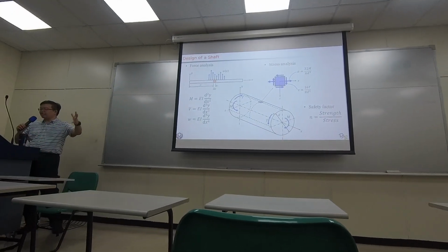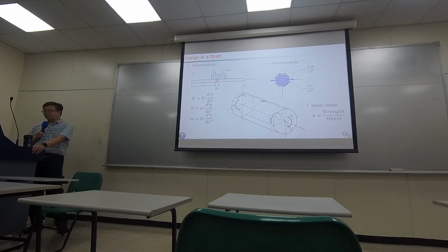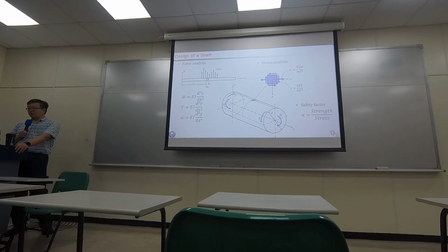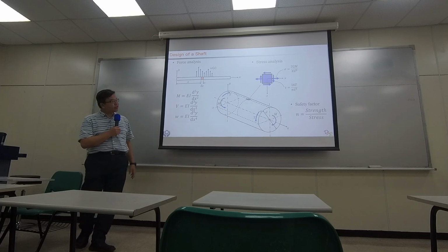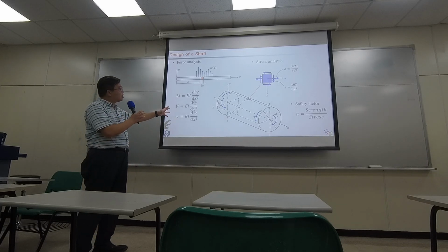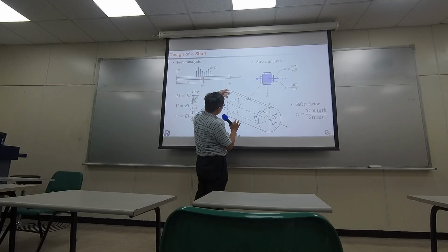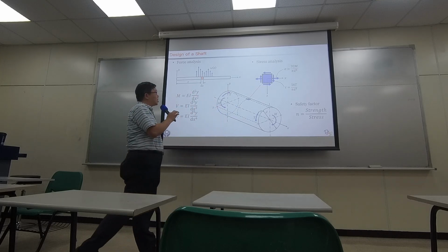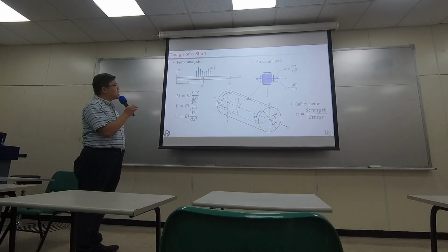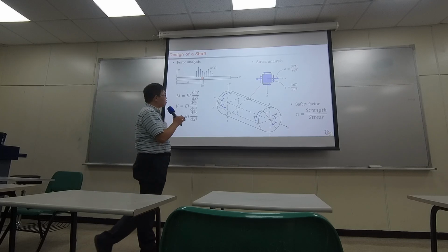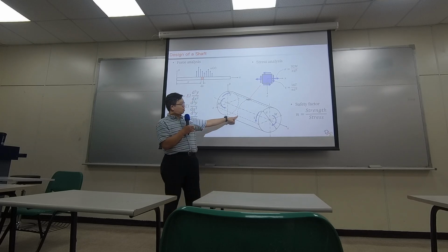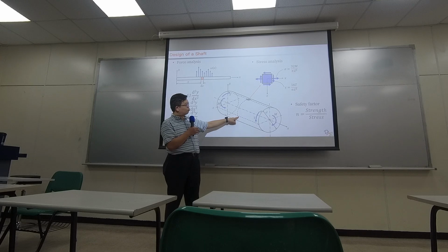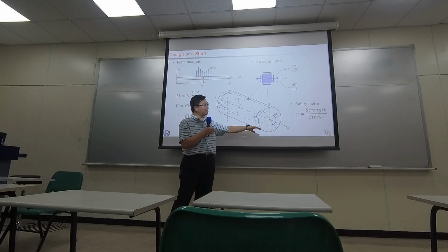At the entire shaft, if we use what we talked about on the shaft, this shaft is carrying bending moments from the side and a twisting moment from the side at the same time. And from yesterday's lecture, we mentioned this point carries more load than the point on the side, because the one on the side is on the neutral plane for bending.